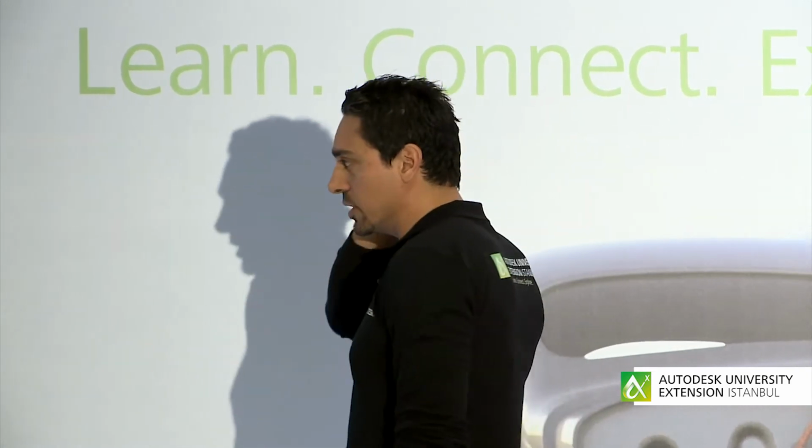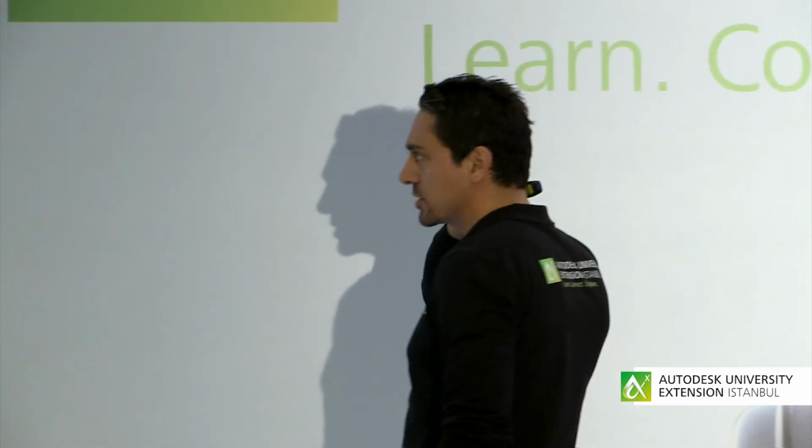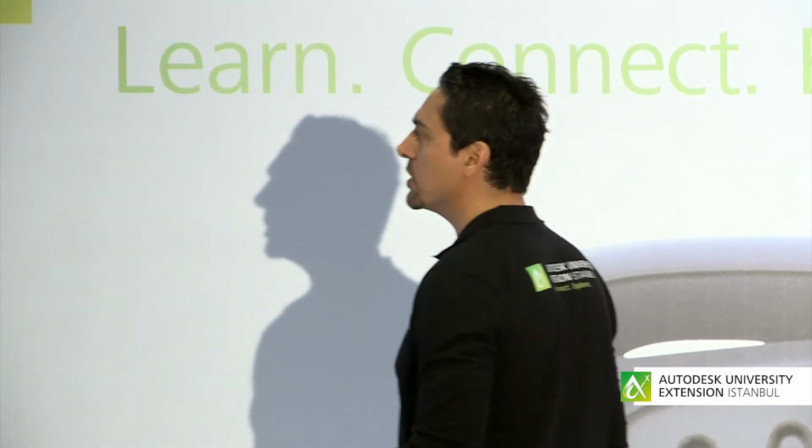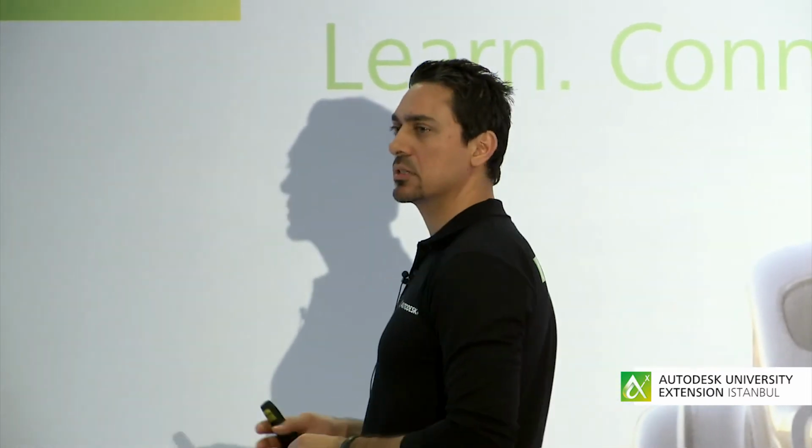Okay, so this is kind of Navisworks. So not only can you go into your factory and run clash or interference detection, you can also walk through the factory. So once you've cleared all the clashes, everything looks good, what will my factory look like? Let me understand the process that these components go through.